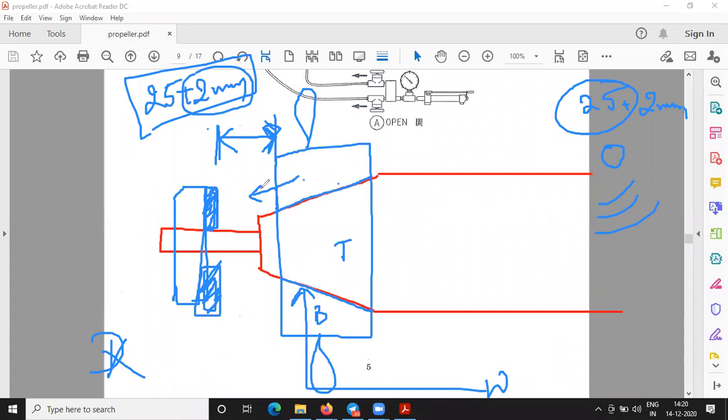The cushions are placed 2 mm apart. You have seen that initially, when 50 bar was given, you adjusted the dial gauge to 0. This 2 mm is the one which ensures that it is clear from all the friction on the tail shaft. Understood? Everything is interrelated here. Once you understand a particular point, it will be easy for you to grasp everything very easily.